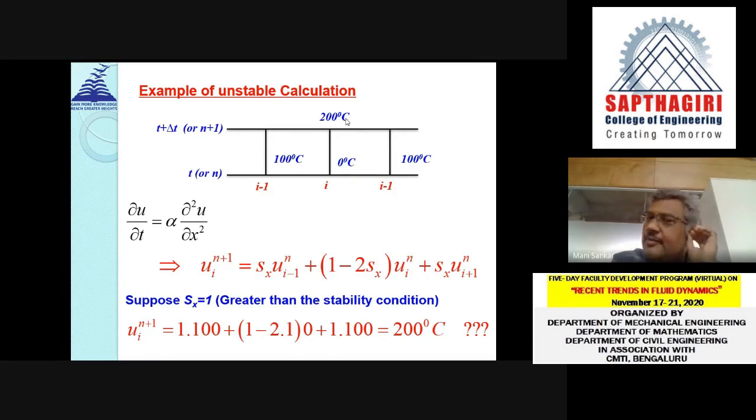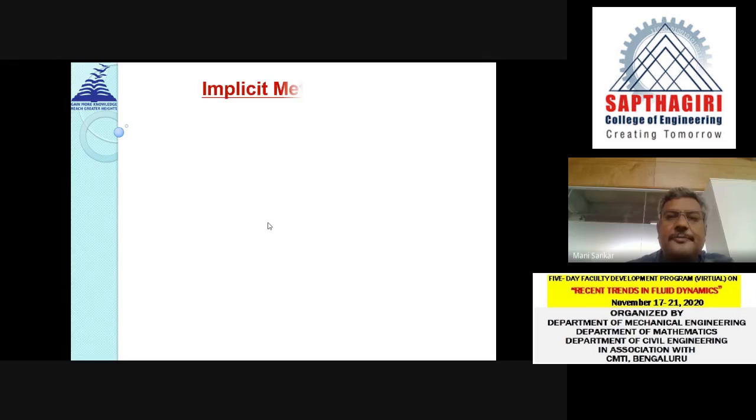When I have a boundary temperature, the interior temperature must be less than the boundary temperature, unless I have some heat generating substance inside the rod. And I don't have anything, because this is the one-dimensional heat conduction equation I use, which doesn't have any other extra term. So this spurious solution I got just because I did not meet the stability restriction posed by this. So this is a severe restriction on the explicit method.